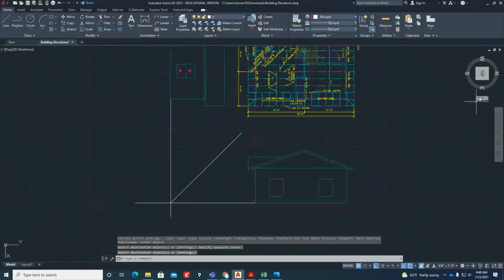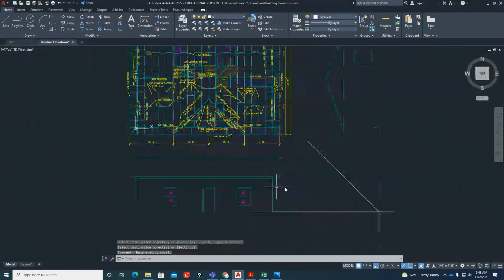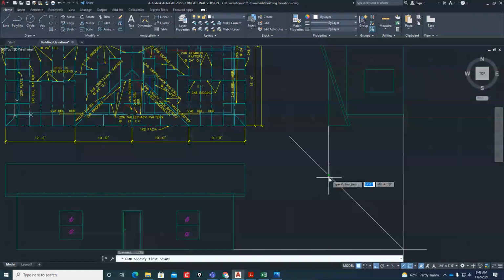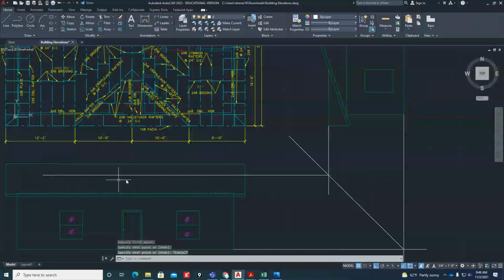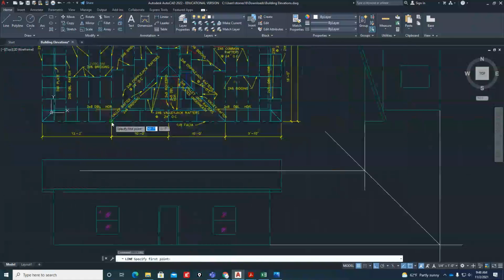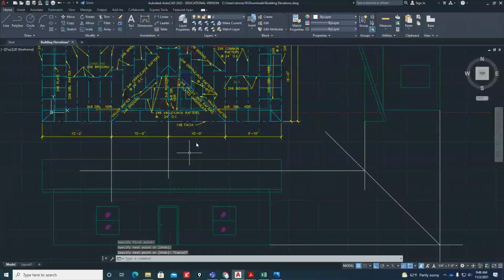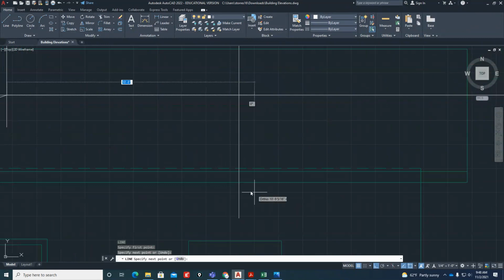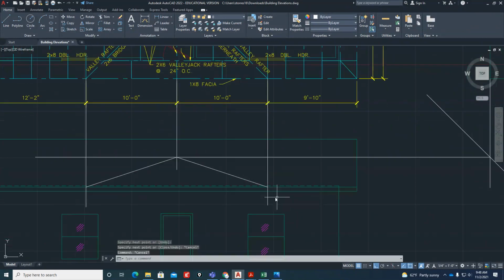Okay. And then to get that front gabled end on the front, I'm going to project this point straight down, which is the top of the little gable, from here across this way. And then it's going to come from this one down this way. This point is pretty much the ridge of the gabled front end. And there it is. It's all projected. And then I just simply connect from this intersection to this intersection back to that intersection.